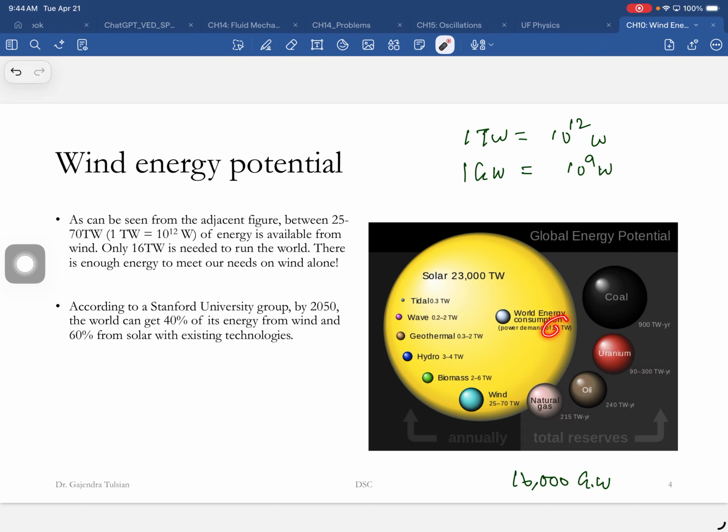So this is very important. Power in wind is proportional to the cube of the wind velocity. Hence, a large portion of the wind energy is available during brief periods of high-speed winds. So when you set up a windmill, you want to make sure you measure wind speeds and set up the windmill right where the wind velocity is the greatest for the longest time.